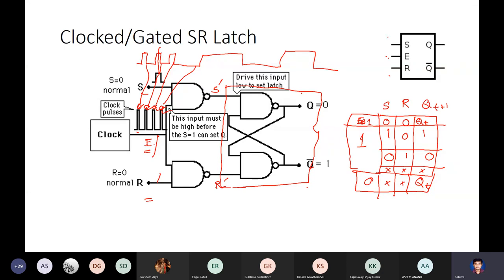So I should keep the latch on for an amount of time which allows for the delay in a single gate. So the clock width should be more than the delay of a single gate, so that it has a tolerance, it allows this time to change the output, but it should not be staying on longer than that, because I want only one operation per clock cycle.